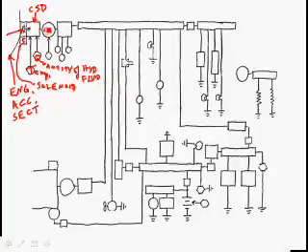And of course, I would want to draw in the AC sine wave, so I would know that that was an AC generator. And of course, we might have a temperature gauge on that in the cockpit. Now this box right here is a generator control unit. And the generator control unit, that's where the leads are going to get put in for the power and for a voltmeter.